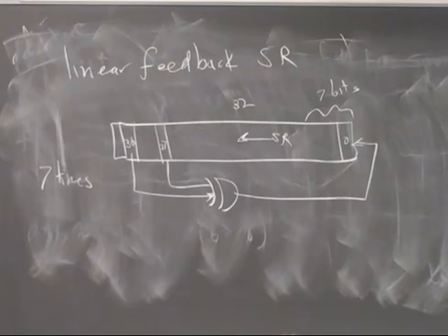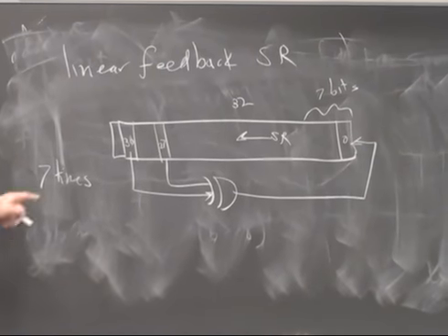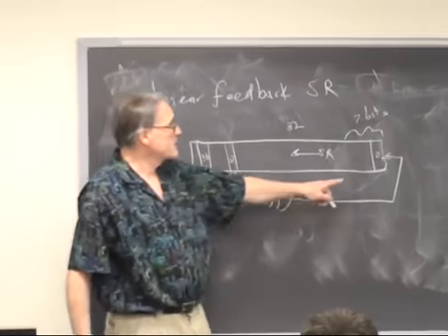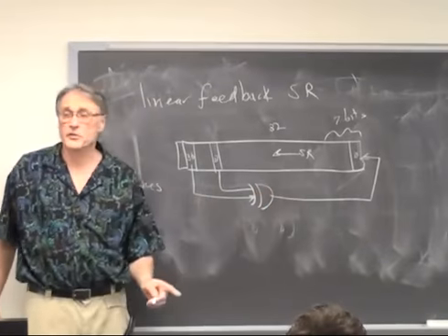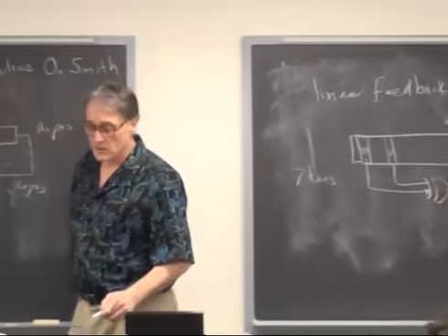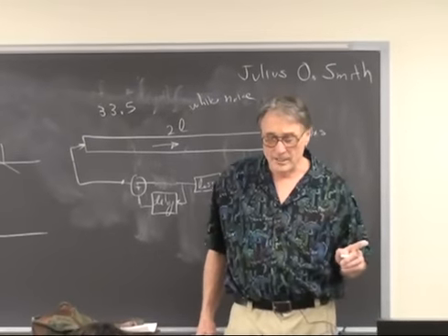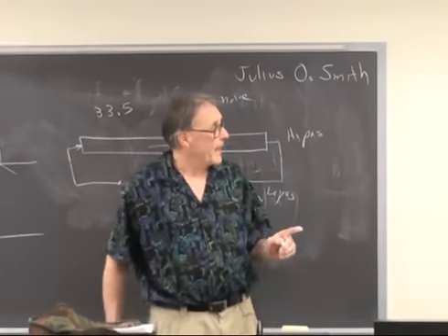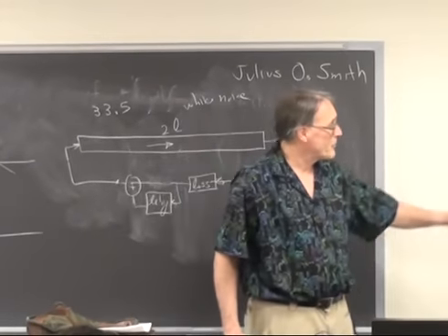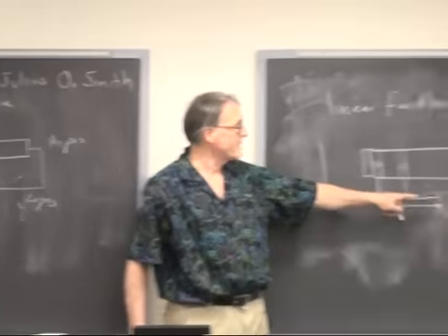So I'll write out the C code for that next time, or you can do it yourself. But this is quick and efficient. It requires one 32-bit shift per time step, and one XOR, and a couple of bit mask operations to pull out bits 30 and 27.